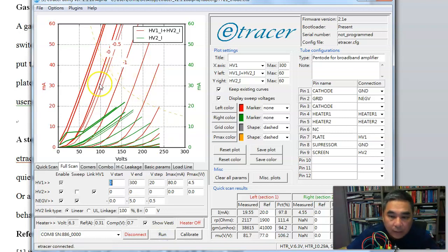Okay, so this one is the plate current measured at 0 volt grid bias, but with 100K in the grid bias supply path. This means the grid current is really causing a problem, and it makes the grid more negative.